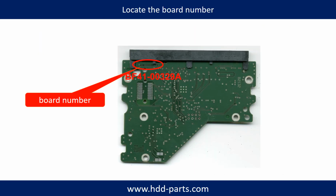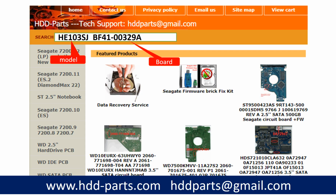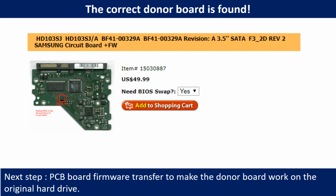Locate the PCB board number. After knowing the hard drive model number and the PCB board number, you may use them as a reference to search for the correct donor board. We found the correct donor PCB board for the hard drive, but this is only the first step. The next step is we have to do the PCB board firmware transfer to make the donor board work on the original hard drive.